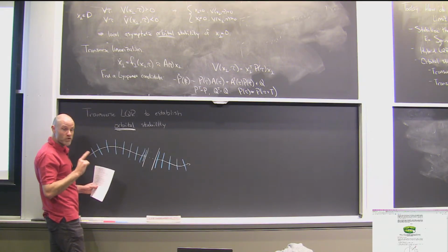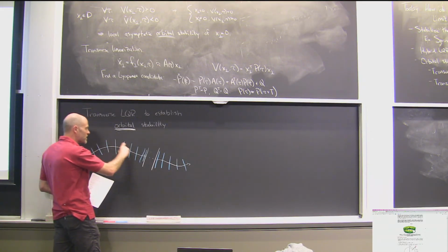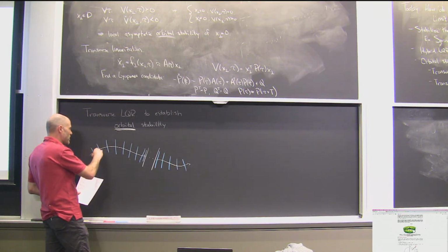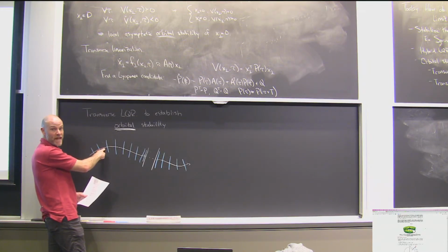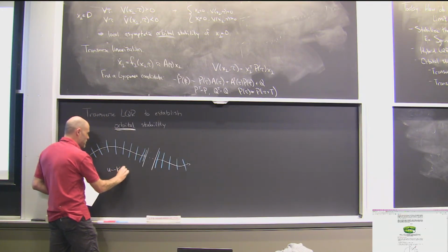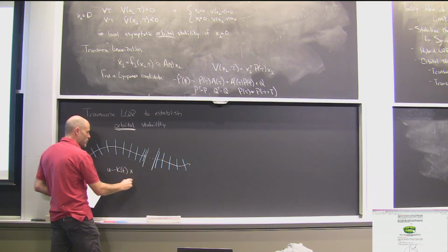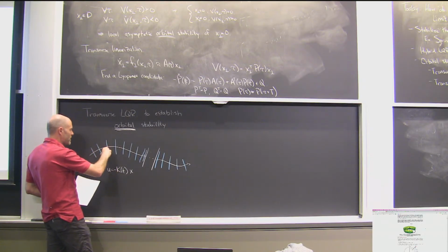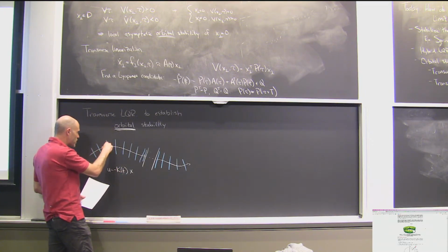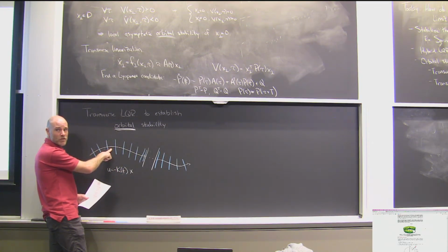This is almost the same as just saying I'm going to do the normal LQR, but I'm going to just, you know, wherever I am, I'm going to find the closest point on my trajectory and use that control. A lot of people want to do that. If they just design a normal LQR in the full coordinates and then just say, well, I won't follow the rigid time schedule, I'll just look up where I am at what's the best time to use.